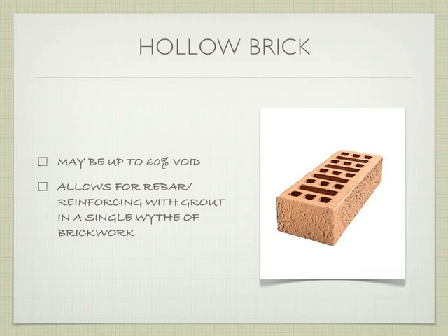Which is basically one vertical row of bricks that can actually kind of withstand structurally, right? So it's not structural in terms that it's not load-bearing, right? But it can support itself and provide like a veneer on the surface of your building, right? So this is the kind of thing that's more for looks than it is for actually structuring the building in the first place.